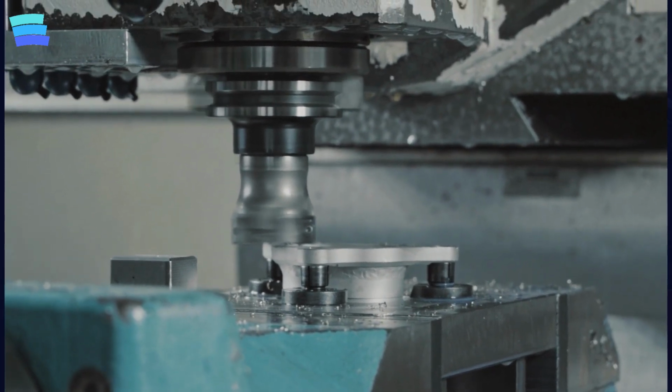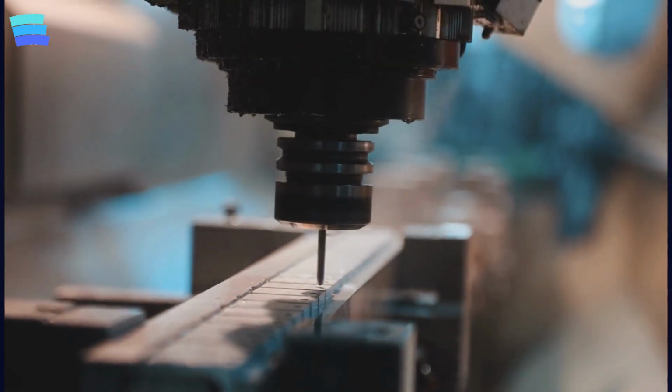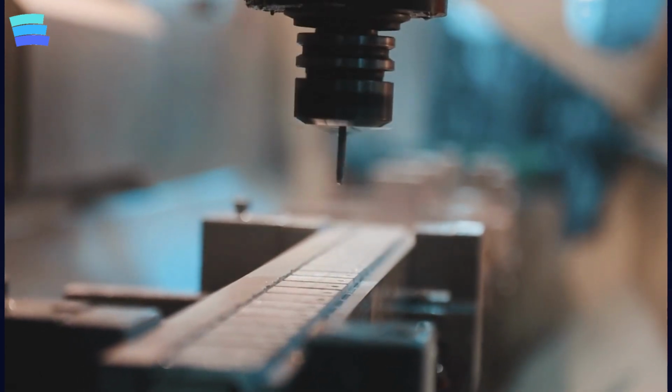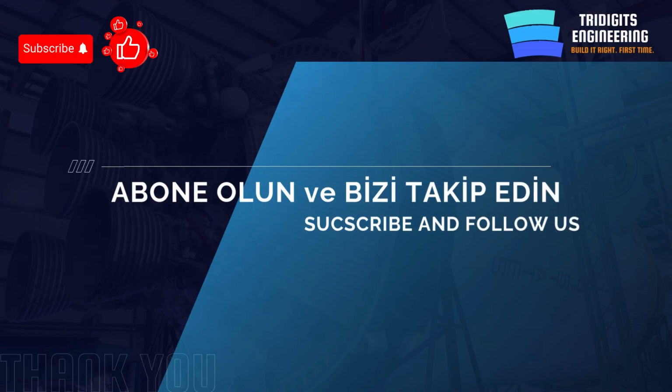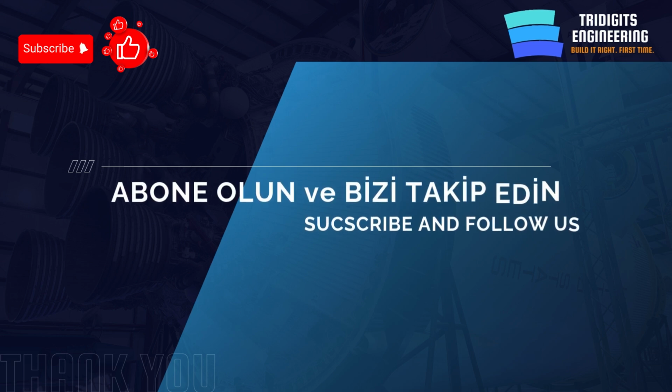For measurement, a caliper is useful for quick checks, while an indicator is a practical tool to detect surface and work-holding-related variation quickly. We will go deeper in the advanced training into tool selection, tool paths, tolerance analysis, and fixture design.